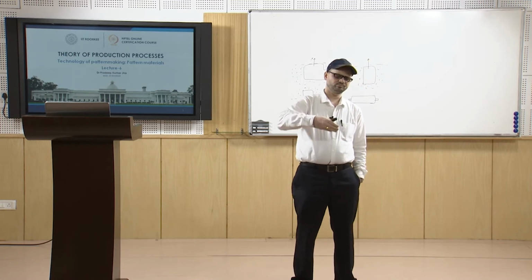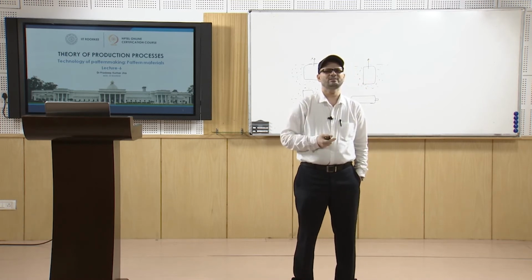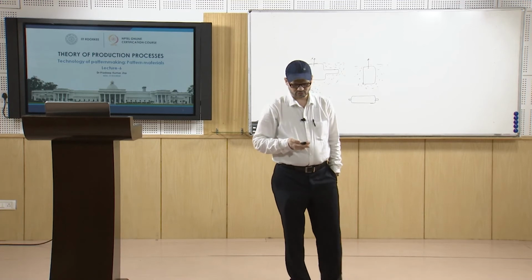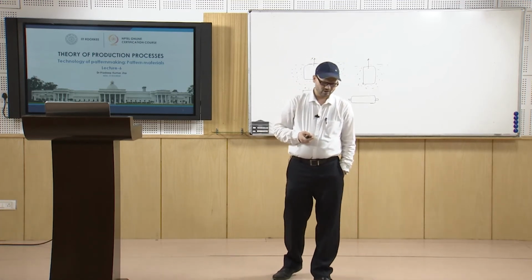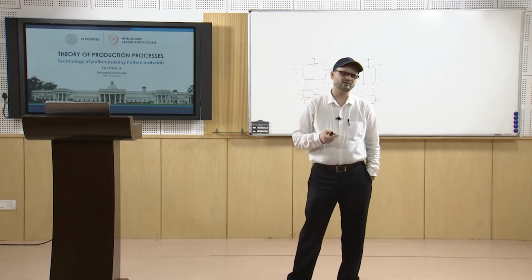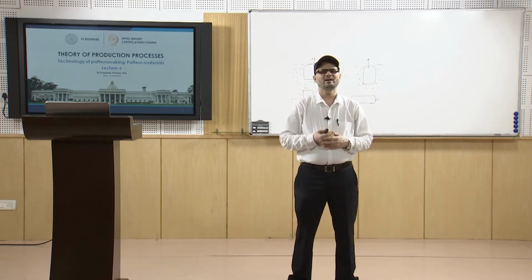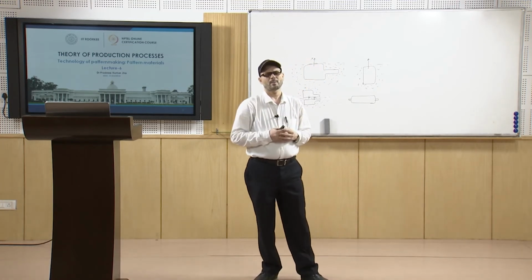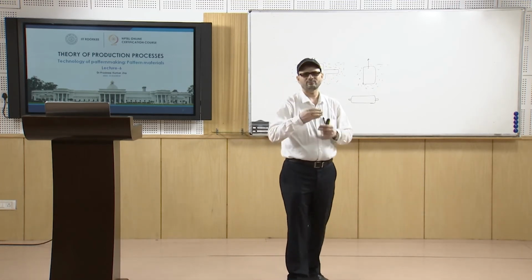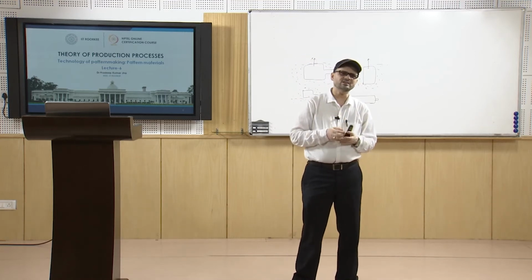So, this is the structure of wood, and normally wood is used when small quantities of castings are required, because if it is used in a very extreme environment for a longer time with sand, then the surface will be rough and that will be reflected on the surface of the casting itself.